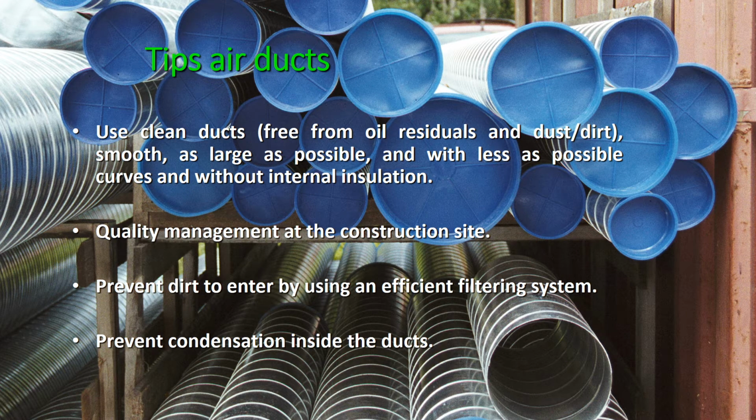For ducts to be able to supply clean air, it is therefore recommended to start with clean ducts, that is, free from oil, residues and dust and dirt accumulated during construction. This can, for example, be established by closing the end of the ducts at the construction site, as you can see here in the picture, and by cleaning all parts in contact with the airflow just before installation. Then it is recommended to select ducts with smooth inner surfaces, that is, avoid sharp-edged curves, turns, transition pieces or self-tapping screws in duct walls, because dirt can accumulate at such places.